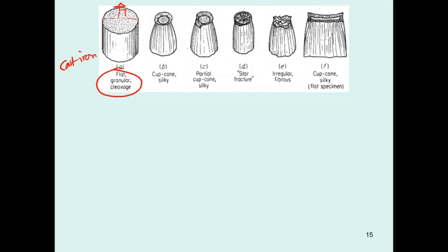For the other, this is going to be for the steel because it has some necking, and this is going to be 45 degrees. This is going to be 90 degrees. This failure is caused by the normal stress. This failure is caused by the shear stress. And you have to notice also how the shear failure looks. If the shape is very smooth and symmetric like this, this is kind of a perfect test.